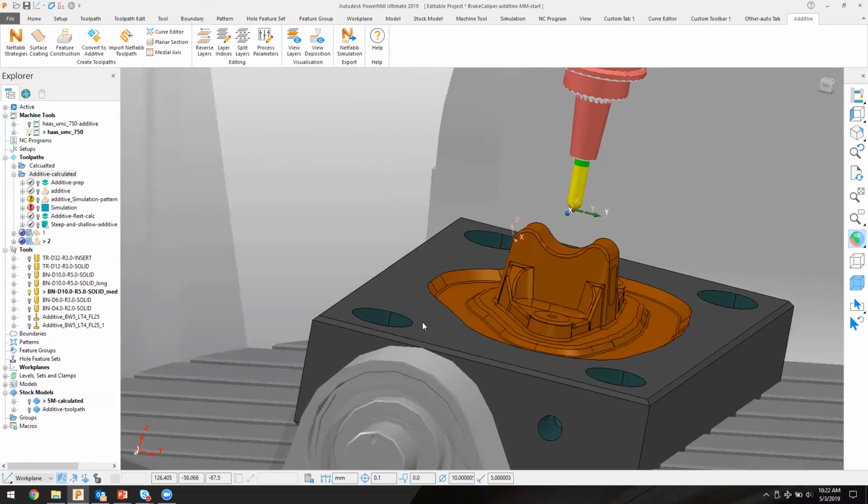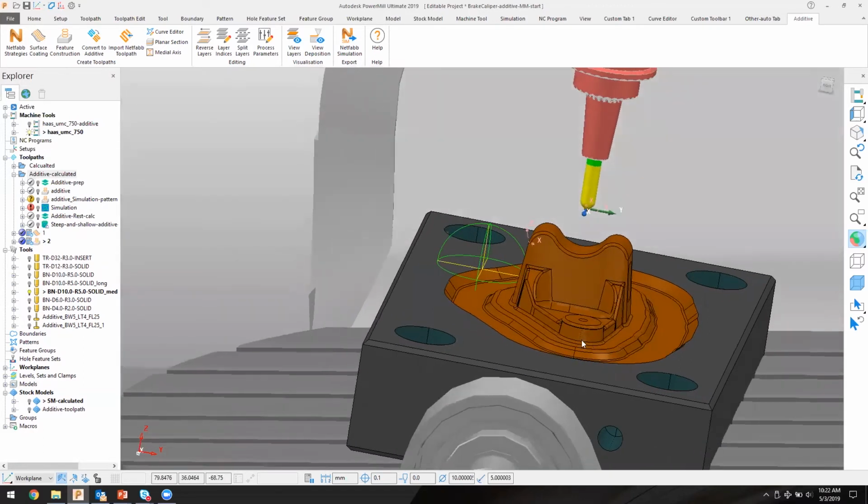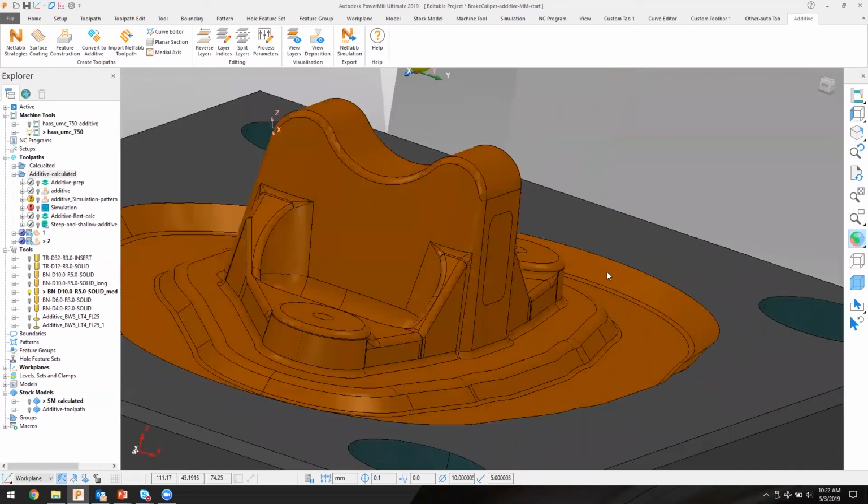In this case, the part that I'm showing is a mold part. And the story that I'm telling here is that we have maybe used this part quite a bit, and this top section here is no longer producing a part with the tolerances that we need. And so instead of making an entirely new part, we are going to cut away the bad portion, then do additive manufacturing to build this back up and refinish once we're done.